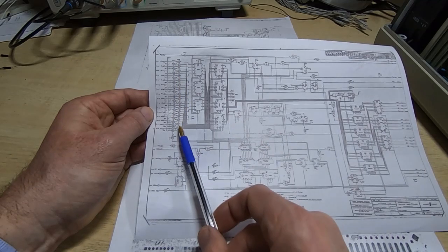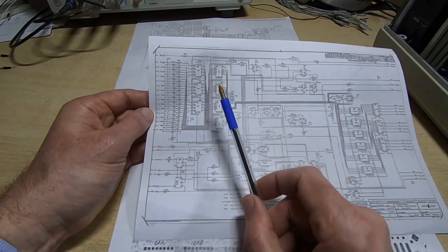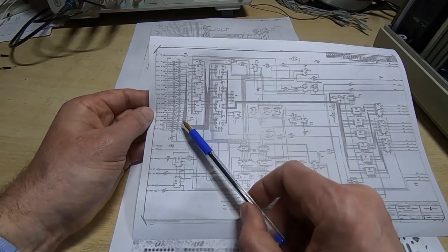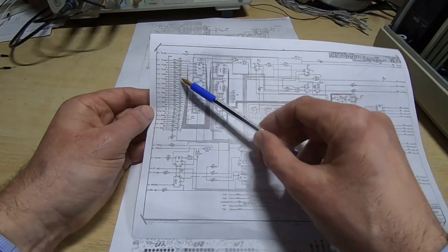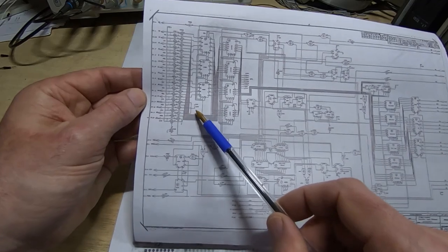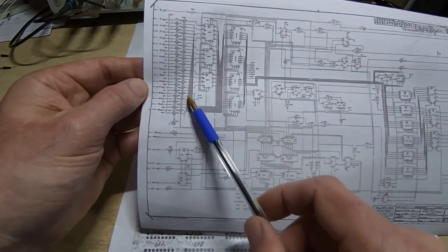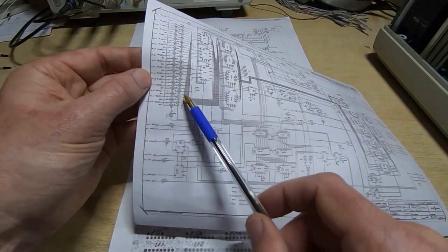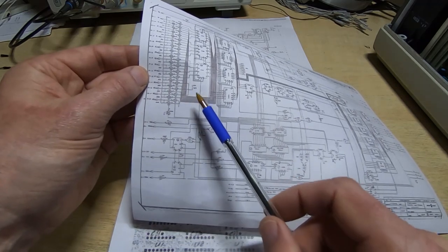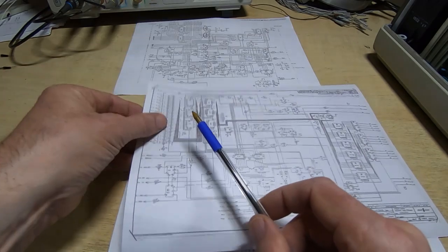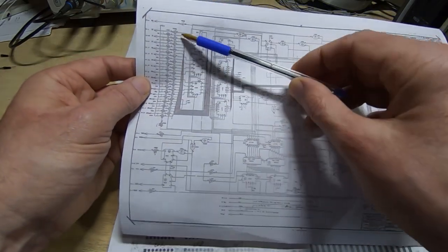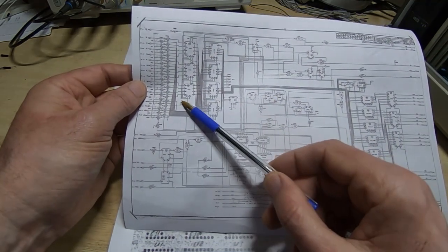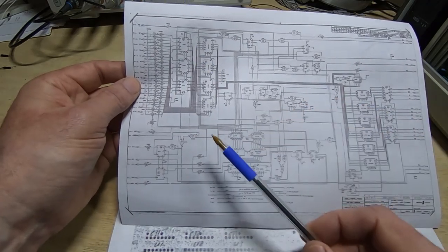So 16 bits coming in. The buffer for the video is at address 7000 hex or 70,000 octal. And so to get us to that base address, we have the 16-bit address value. You probably can't see this, but if you look on the schematic for this, the upper 4 bits are hard-coded to give us a value of 0111, and that takes us to a start value of 70,000. The other remaining 12 bits are to allow us to increment through that buffer. So it takes us from 70,000 octal upwards, of course, as we count.